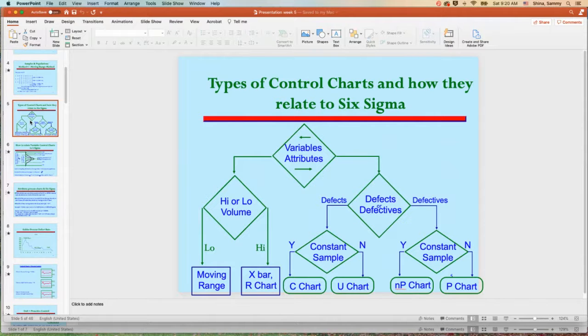So if the measurement is inside the control limits, everything is fine, and the operator might do this at the beginning of the shift or every 2 hours on the shift, depending on the system. Obviously, if you have a good quality system in place, you do it once a day or once a shift. If you have systematic problems, then you might do it more frequently, like I said, every 2 hours.